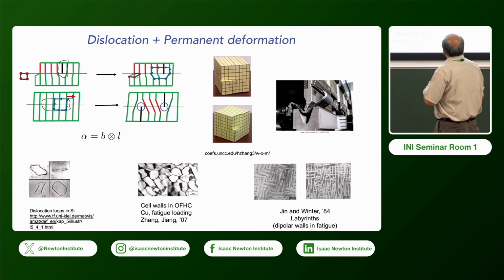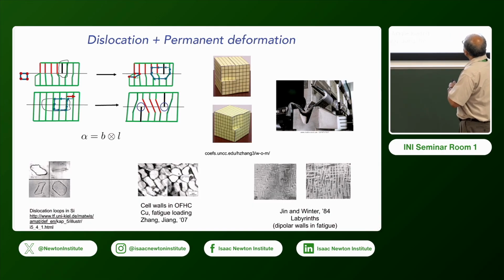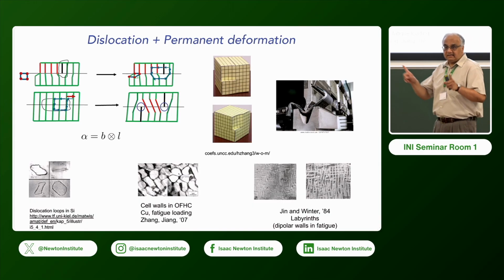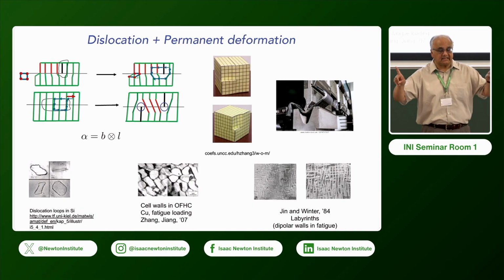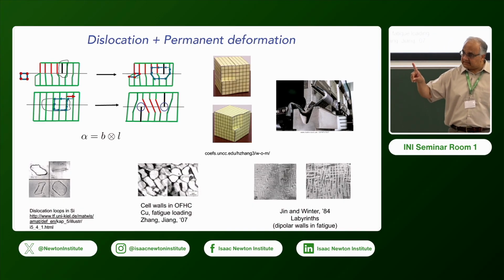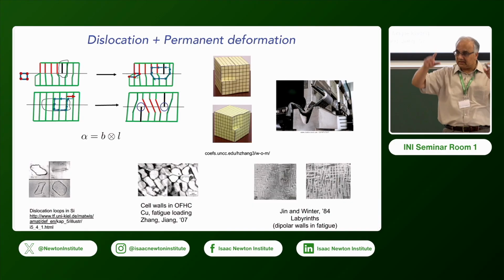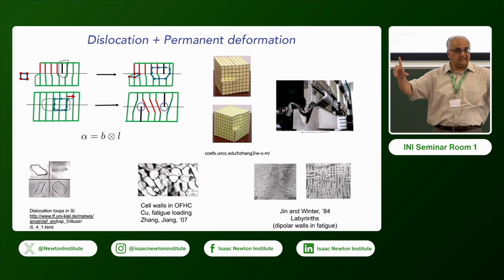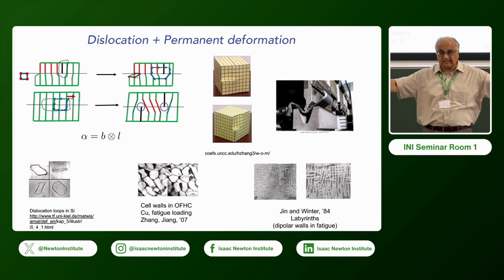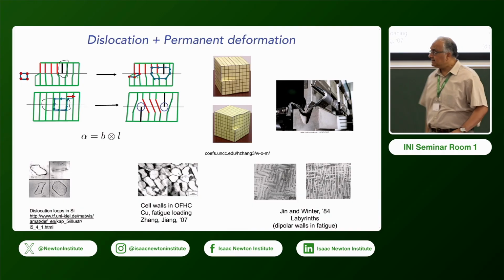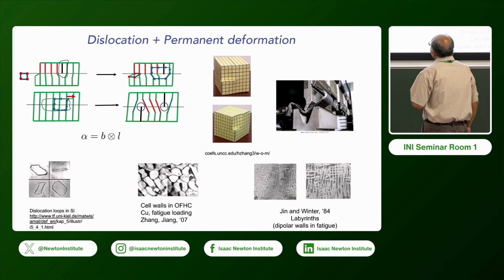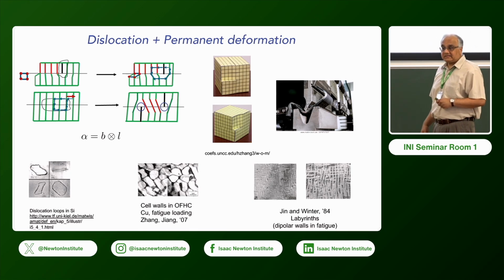The other thing to keep in mind related to dislocation, you see that this is called the core. Around here, the bonds are going to be messed up. So there's going to be stress, even if you don't put any loads. This is a characteristic of dislocations in the body, that there's going to be stress in the body, and these are actually fairly long range. In 2D it's 1 over r decay, even in a linear elastic medium. So this is a pretty high level of stress.